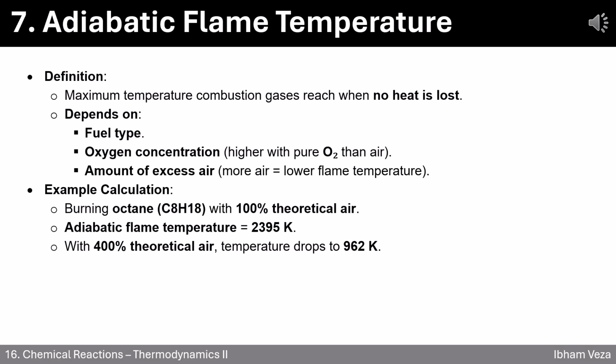Several factors affect this temperature. First, the type of fuel. Different fuels release different amounts of energy. Second, oxygen concentration. Using pure oxygen instead of air raises the flame temperature because you're burning with more oxygen and less inert nitrogen. Third, the amount of excess air. Adding more air actually lowers the flame temperature because it absorbs heat without reacting.